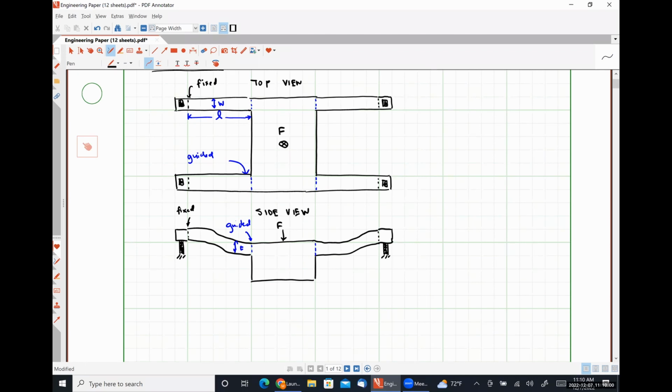So as I said a couple of moments ago, each of the beams which connect the central plate to the outside anchor points is considered a guided beam spring, okay? The most simplified approach to analyzing a structure like this is to consider each guided beam spring as two cantilevers with a length of L/2 in series.